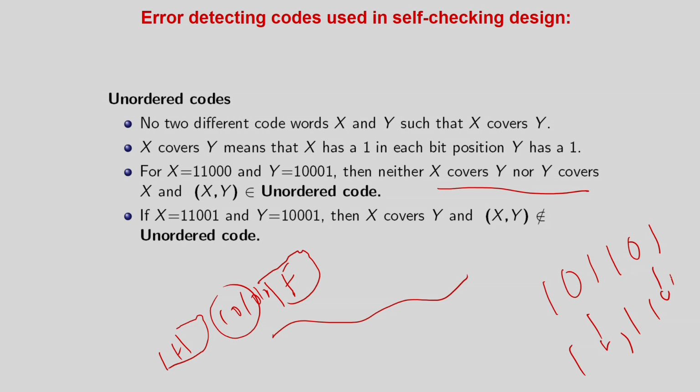So if some data is flowing from one place to another over the air, and there is lightning or noise, it tries to flip the bits in one direction, because it is not an error as in a circuit. In a circuit, the error is a stuck-at fault or some fault in a gate which gets reflected in the output, with bits getting flipped from 0 to 1 or 1 to 0. But coding theory was mainly used for detecting errors in the communication channel. In a communication channel, errors do not happen because of faults in the wires. They happen because of interference, lightning or external noise.